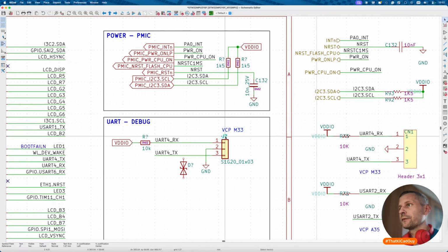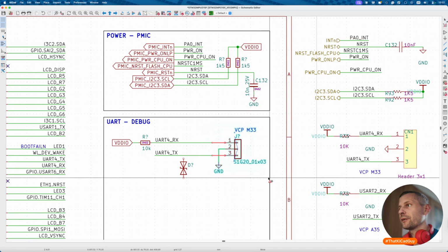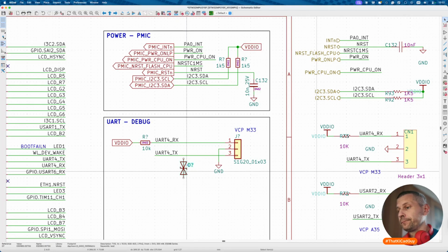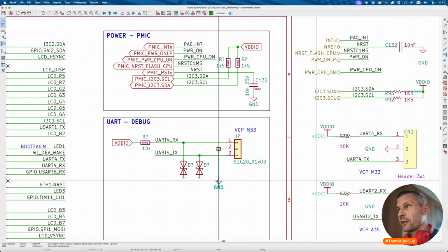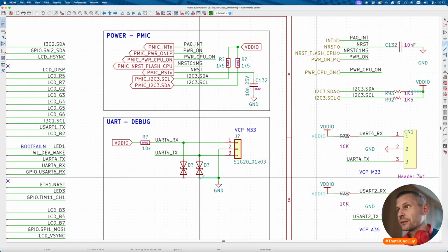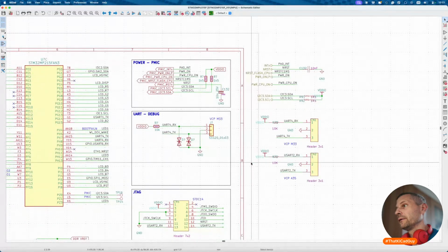For some reason, the reference design creators ignore the ESD protection. I don't know why. You definitely don't want your design fail because of some sparks on your fingertips.